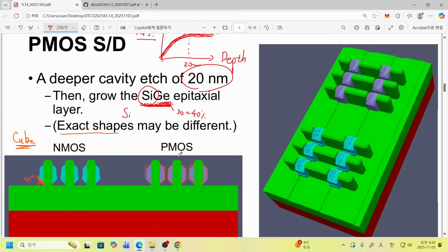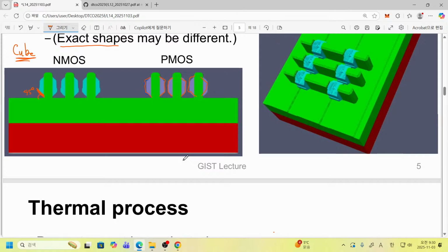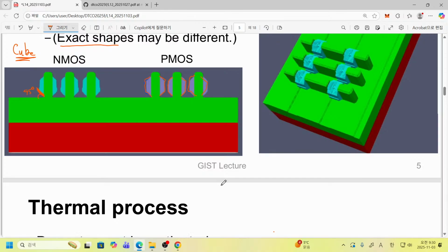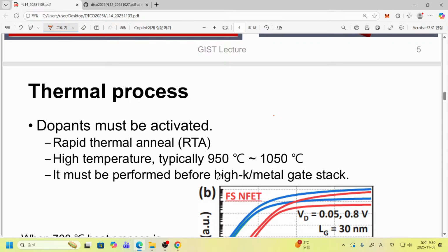So now let's come back to our case. When we perform this kind of silicon epi or silicon germanium epi, we intentionally introduce some portion of impurity atoms. Yes, so we have many impurity atoms, but there is no guarantee that they are taking the place of silicon atoms. They are not belonging to the crystal structure. They are just aliens in this silicon system.